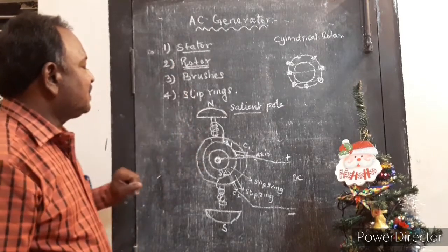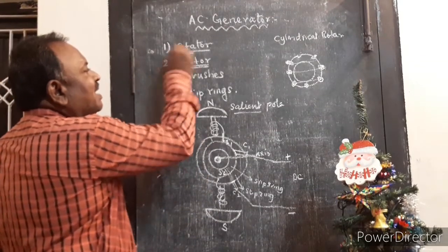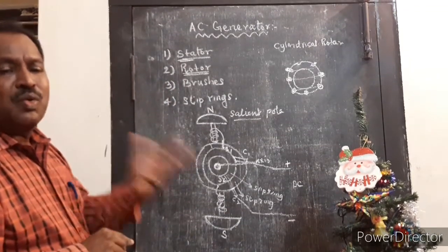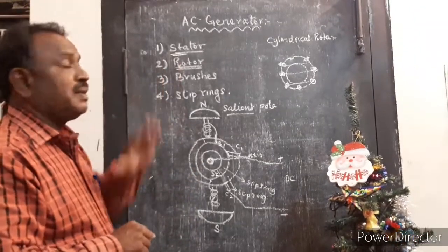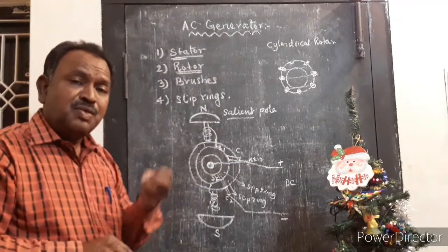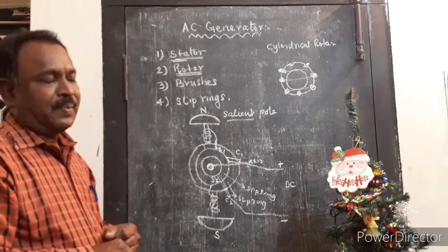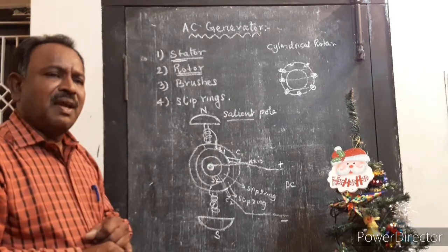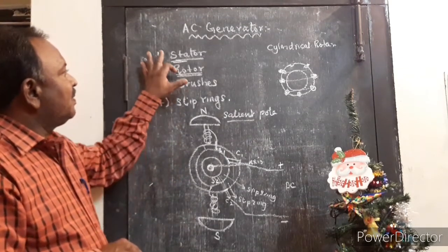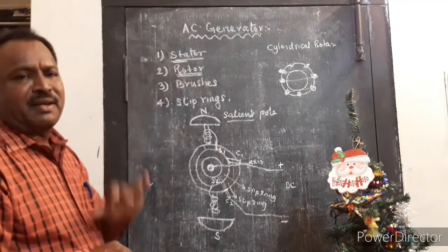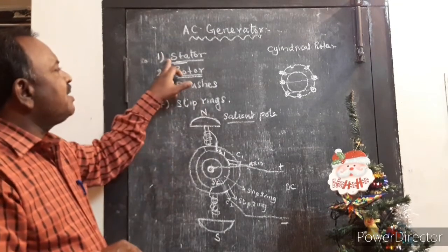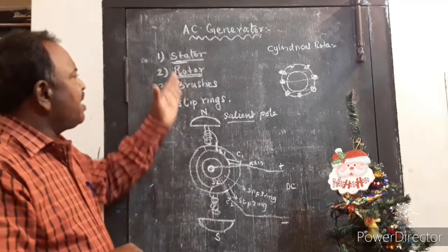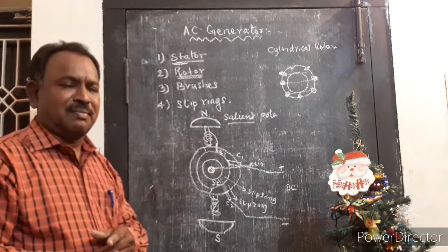we can take the output directly from the armature coil connected to the stator. There is no need for slip rings to take the produced EMF from the coil. Secondly, by selecting the stator as the armature coil, we can wind the armature coil firmly to the stator, and insulating this coil is very simple. So there is no problem in providing insulation for the armature coil.